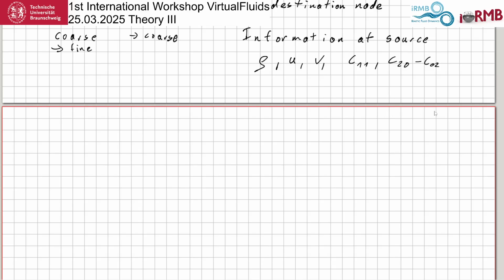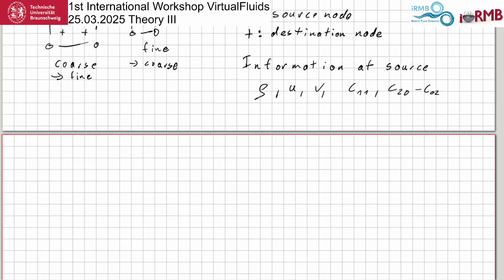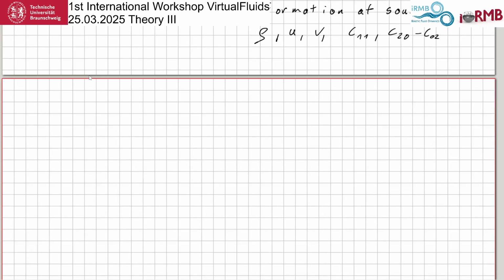So, how are we going to do this? We don't want to interpolate these directly, but we want to have second order interpolation on these cells. Now you notice if you use these 4 nodes, you don't get a second order interpolation. You get only bilinear interpolation, or in 3 dimensions trilinear interpolation. So in order to amend this, we use our knowledge from asymptotic analysis.